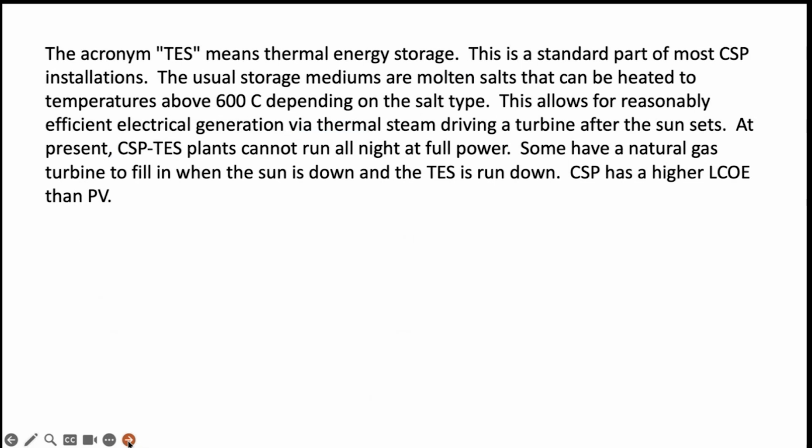So this acronym TES means thermal energy storage. This is a standard part of most concentrated solar plants. The usual medium is molten salt that can be heated to temperatures up to 600 degrees, depending on the type of salt. So you can store that once it's heated and then use that to generate electricity via thermal steam driving a turbine after the sun sets.